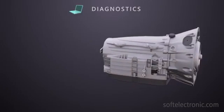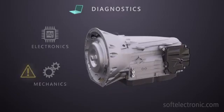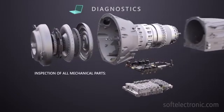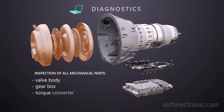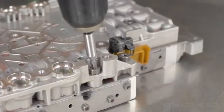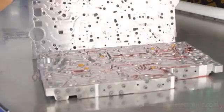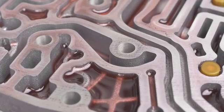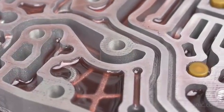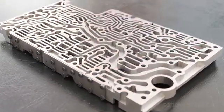If a mechanical defect in the automatic transmission is determined during the overall diagnostics, the mechatronic is then scheduled for dismantling and inspection of all mechanical components, which includes the valve body, gearbox, and torque converter. The valve body is sent to the specialized department for maintenance, and if needed, a repair is carried out. It's disassembled into its composite elements, and after that, a test for the presence of antifreeze in the transmission fluid is performed. The oil passages in the plates are visually inspected for residue and solid foreign particles. After these procedures, the valve body is cleaned up.